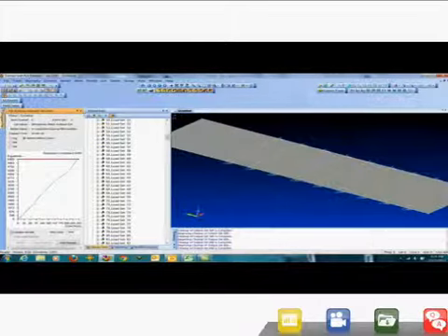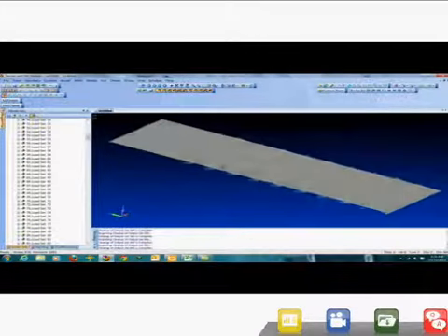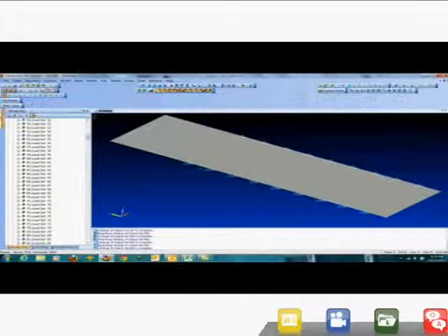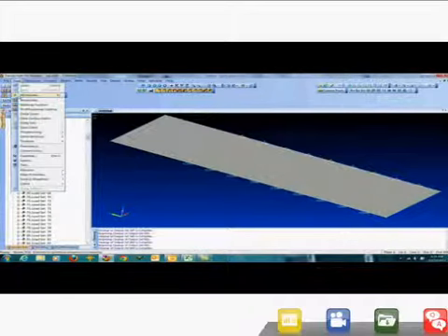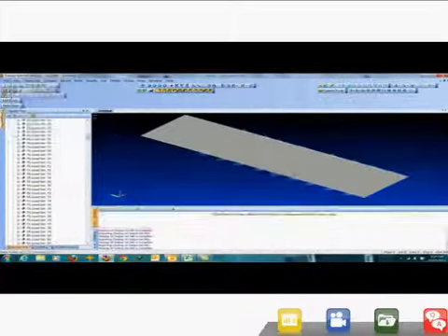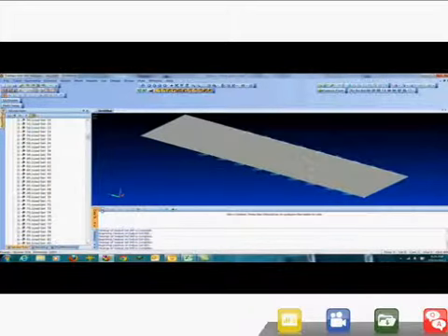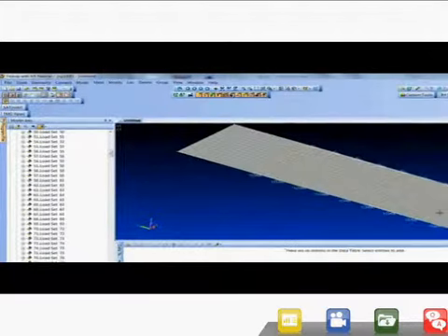Now the ranking's pretty straightforward. We actually wrote a tool to do this in the last maintenance release of FEMAP. Requires that I bring up the data table. So I'm just going to pop open the FEMAP data table, unlock it. And this is the neat thing. Let's say the first thing we want to do is just find the max von Mises stresses for the plates.